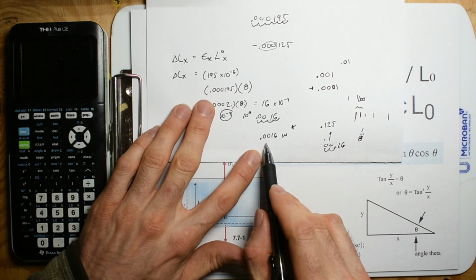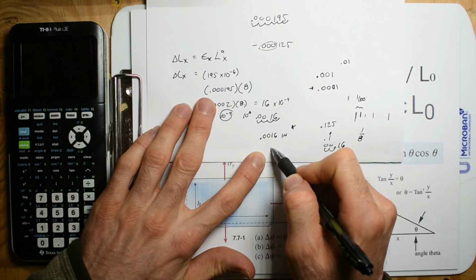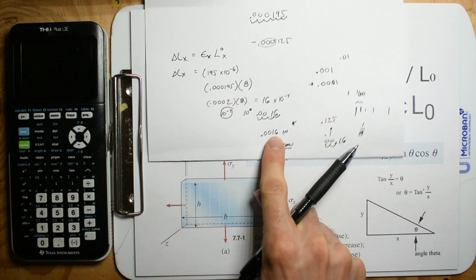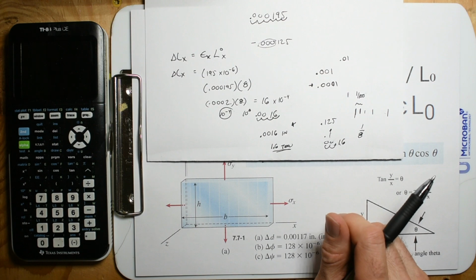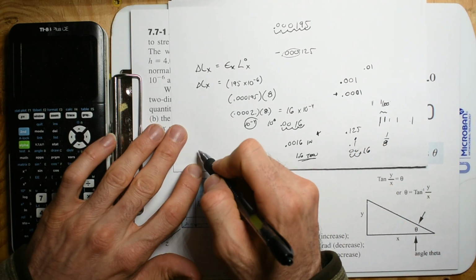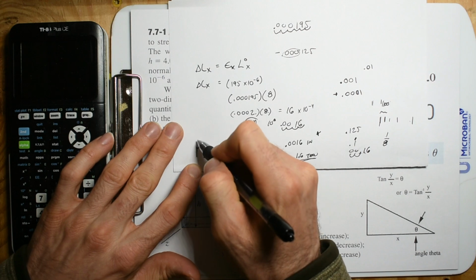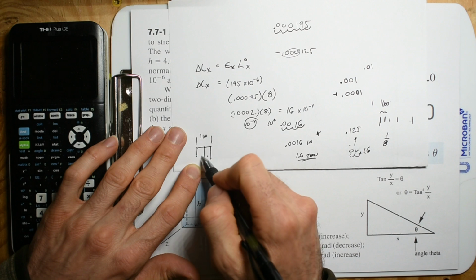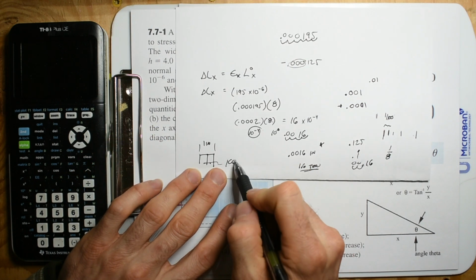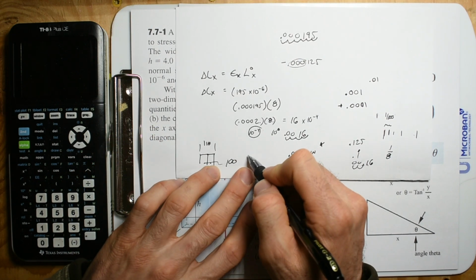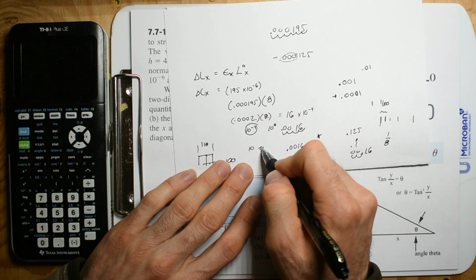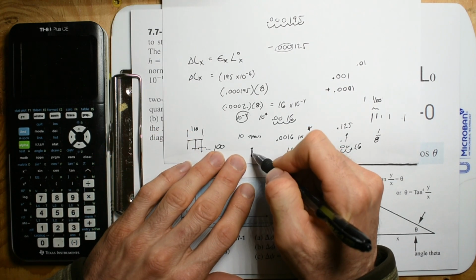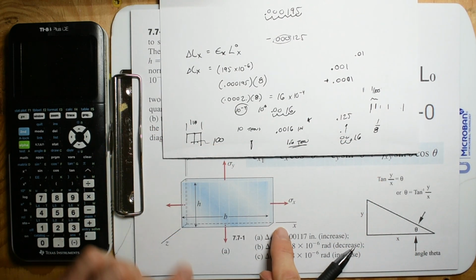And so what number did we pull? We pulled 1.6 thou. So we're more than a thousandth of an inch. And this one's pretty cool, because if you take 2 stacks of playing cards and put them together, you get about 1 inch. There's about 50 in both decks, so you get about 100 cards, and that's going to be 100 cards per inch. So each card is 10 thousandths. If you had a playing card, a tenth of that is going to be the change in length in that direction.